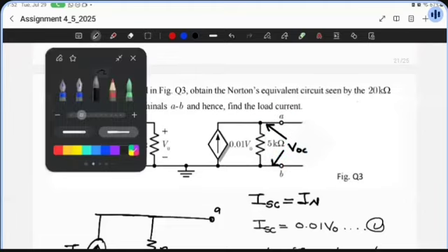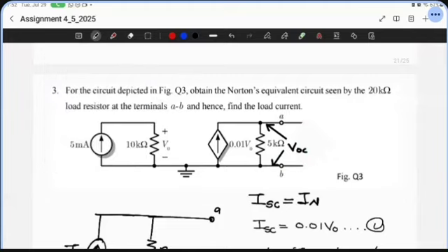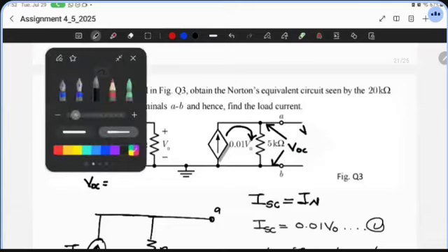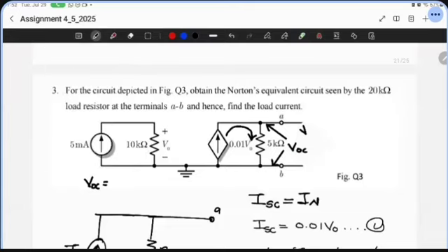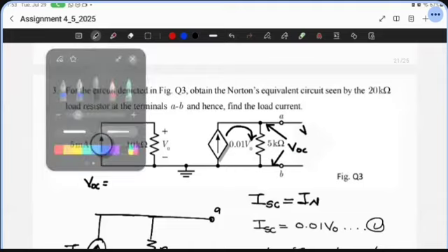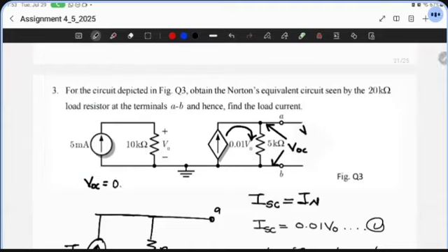So how are we going to do that? Well, in this case, notice that with this line empty here, knowing what the 5 kilo is using becomes easy, because all this current will be going towards the 5 kilo. So the voltage VOC will now be equal to the current being supplied multiplying the resistance, which is that 5 kilo. So this is what we're going to have.